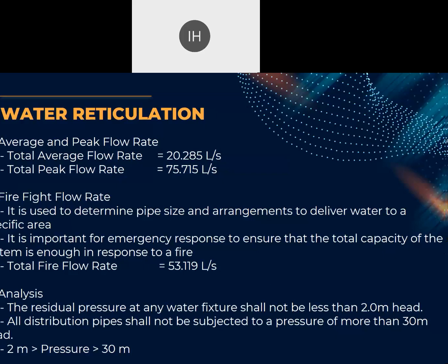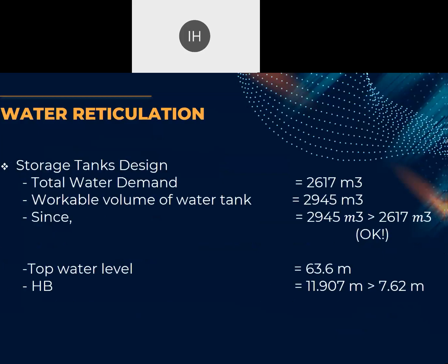Lastly, for analysis, the residual pressure at any water fixture shall not be less than 2 meter head. All distribution pipes shall not be subjected to a pressure of more than 30 meter head. Storage tank design.